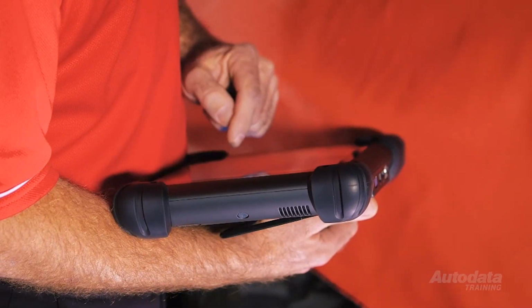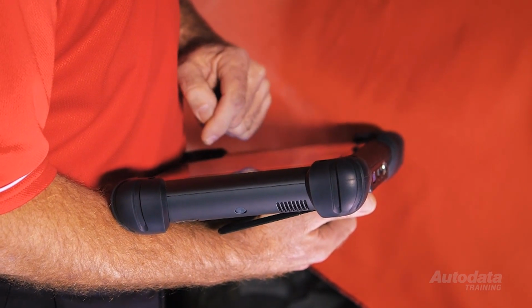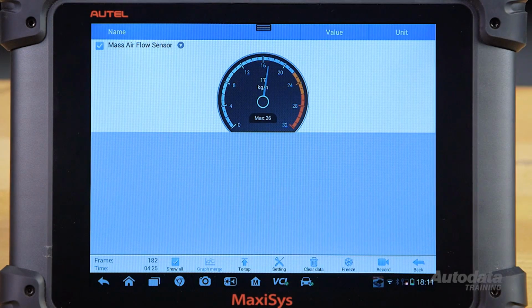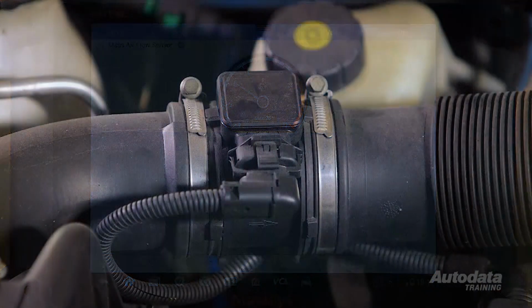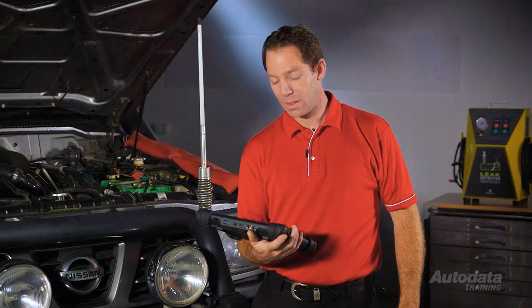With the engine idling, command the EGR valve from closed to open with a scan tool. Verify the MAF or MAP sensor data parameters change value when commanded. This tells us that there is exhaust gas flow to the intake manifold. The MAF or MAP value is changing due to the reduction in fresh air flow to the manifold.